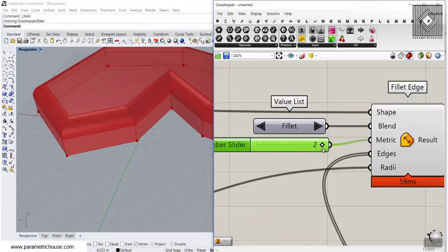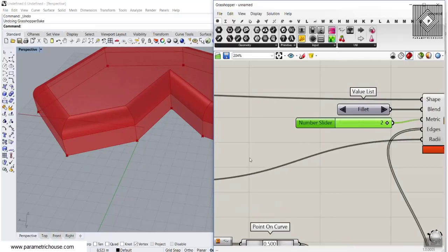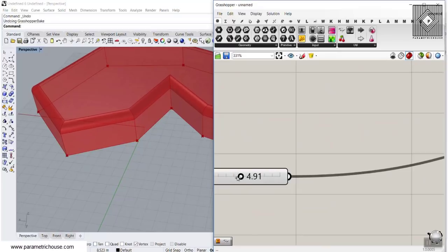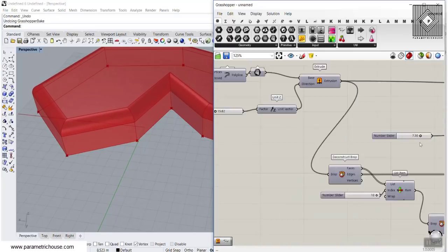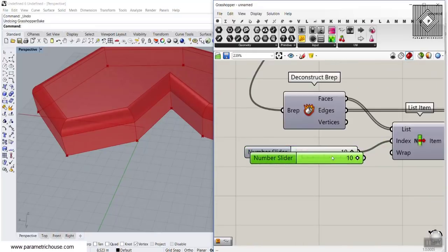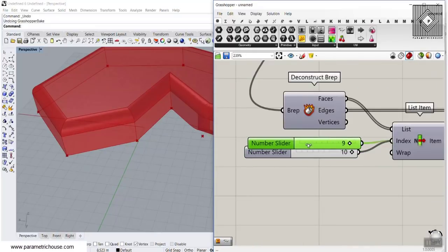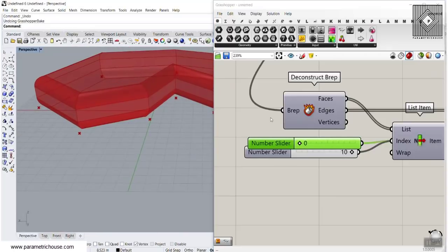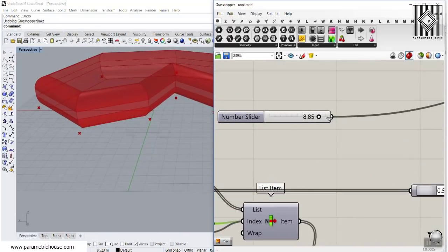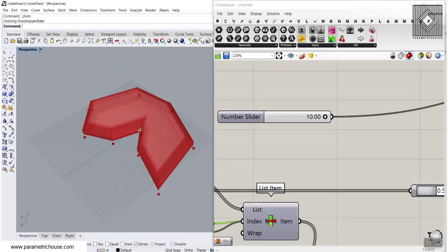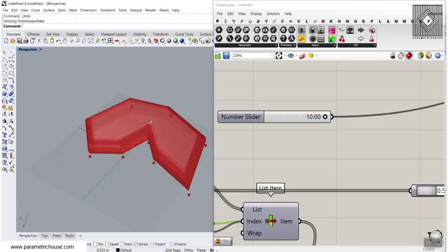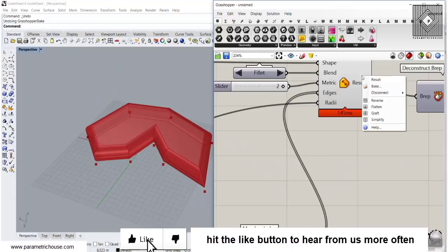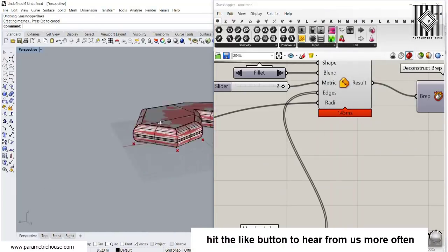1 doesn't really change that, but the 2, the distance here, is controlled with this number. So this is a way you can just use that to have a standard distance and a fixed distance between those edges if you want to. And remember, always you can have different faces with the shift key. Let's just give this to the 0 and produce, if you are going to produce something for industrial users, you can also use this technique to have it as the fillet edge tool. Here we go.